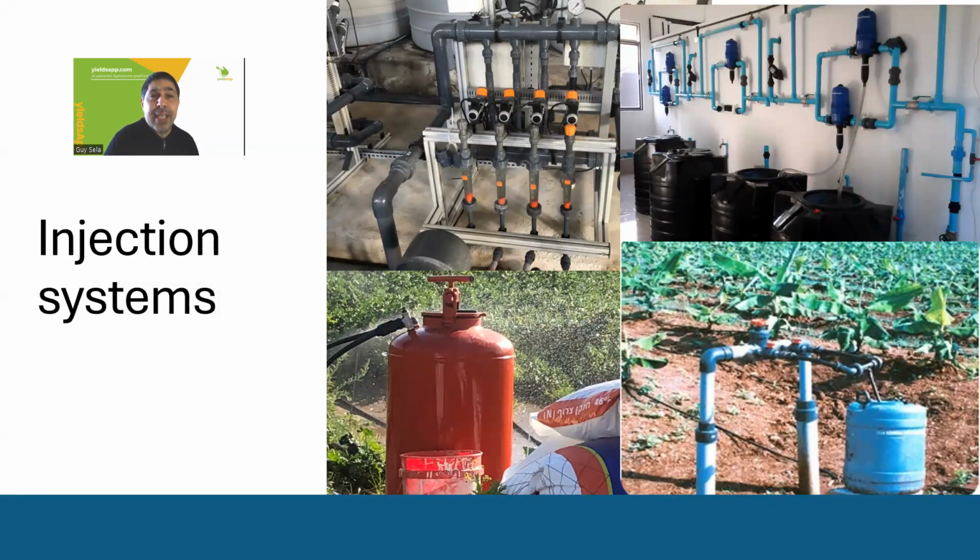And that's the injection ratio, is how much, all right, of the stock solution. We don't even talk sometimes, when we talk about injection ratio, about what we have in the tank. We're just talking about what's the injection ratio of the system, all right? So we can adjust it. And in the automated systems, we have more control because we have the computer, we set up the injection ratio for each injector here. And I don't know if you noticed what I've just said, you can even set a specific injection ratio for each nutrient, each fertilizer.